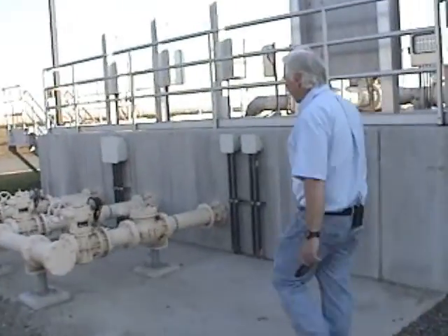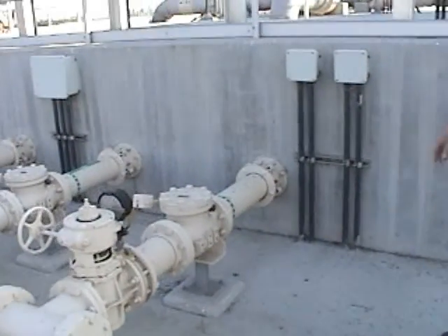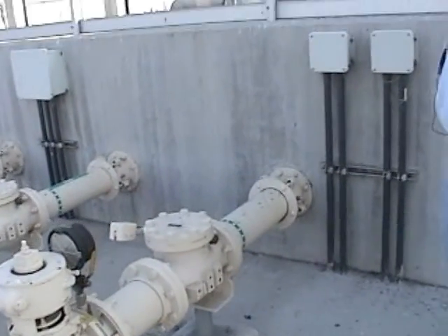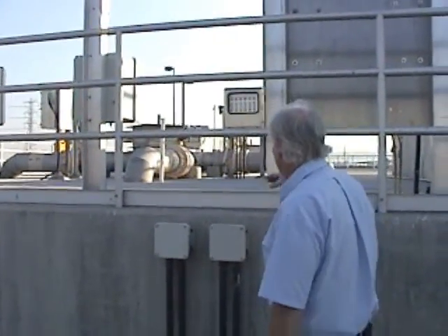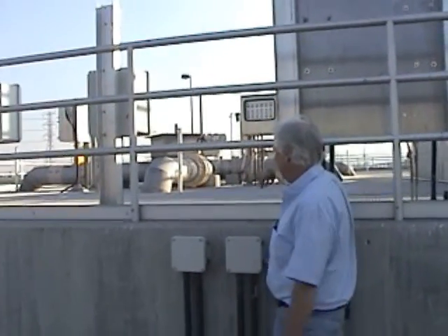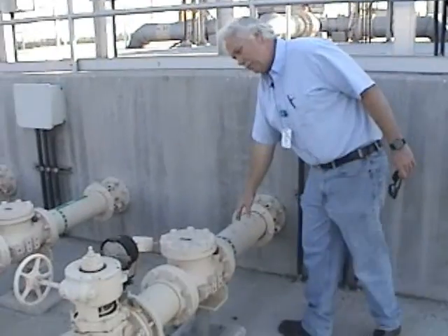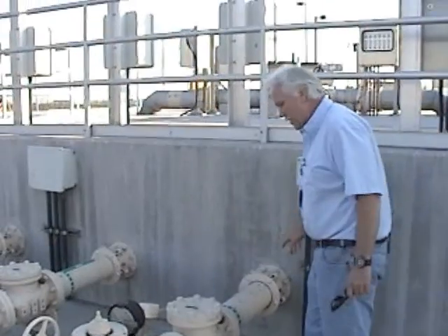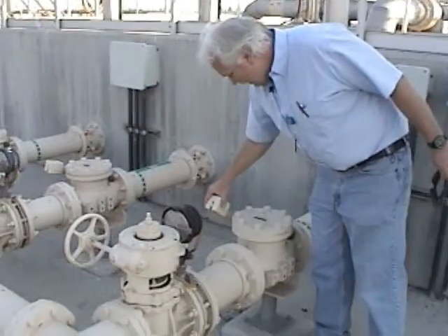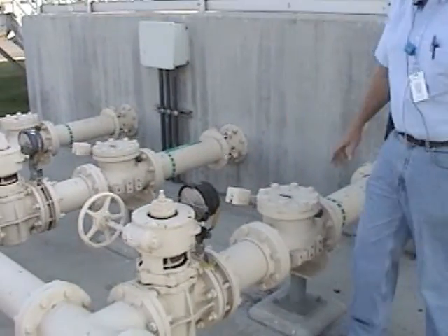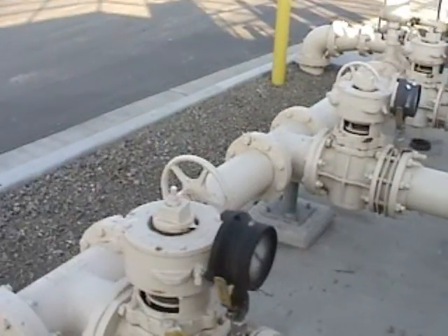These are the backwash water pumps for the filters. They're continuously backwashing, so each of the online filters is discharging its backwash water into a network of piping, which drops flow into this channel behind me. I want to say it's about 20 feet deep, and then these pumps are picking up the backwash water and returning it to the head of the plant. There should always be at least one of these running. As you're looking at it, you can see this check valve. This one's online. This is a pressure indicator on what the pump's discharging.